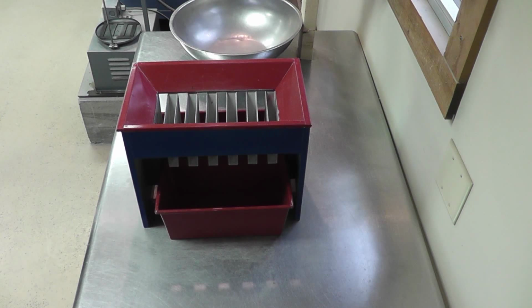For dry fine aggregate in which the entire sample will pass the 3/8 of an inch sieve, the minimum width of the chutes shall be at least 50% larger than the largest particles in the sample, with a maximum width of 3/4 of an inch.